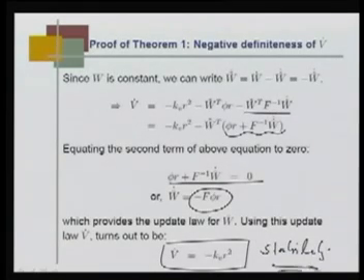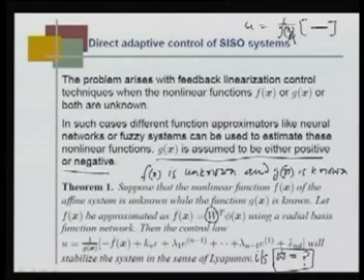So, the stability comes when w hat dot, the derivative of the weight update law for the radial basis function network that is approximating the unknown f x, should be minus F phi r. So, if you go back, I asked this question: will this stabilize the system in the sense of Lyapunov if w hat dot is F phi r?